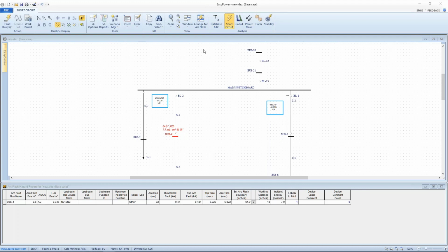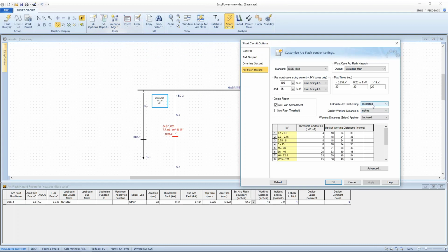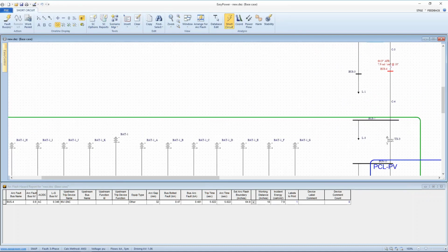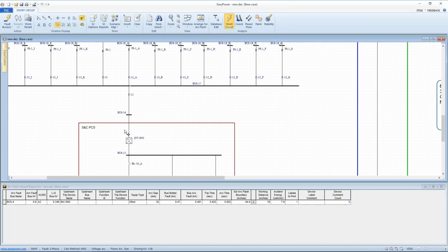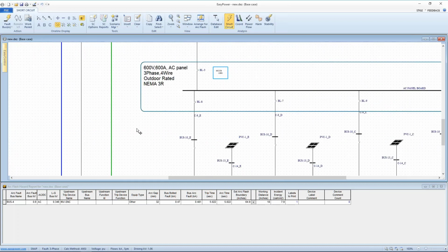Okay, so where does this leave us? First of all, we're utilizing the integrated method because it's going to be more accurate in terms of these long fault clearing times. We've specifically designated which tripping device will protect, in this case, the batteries from a fault upstream from a total collector. We've also identified a potential that either we need another inline fuse for the total current, or we need to understand what the inverter can protect us for from that group contribution.